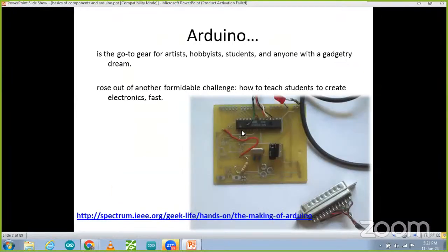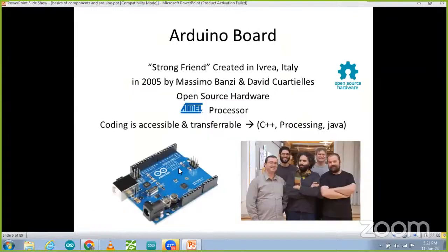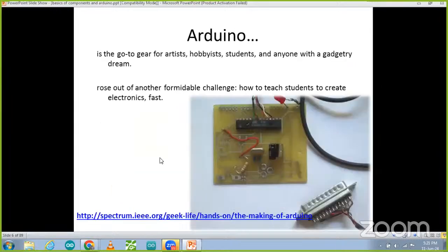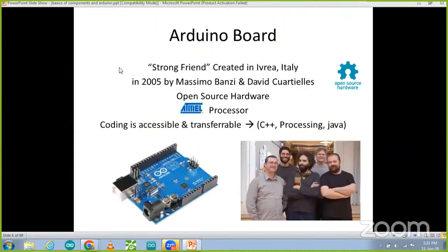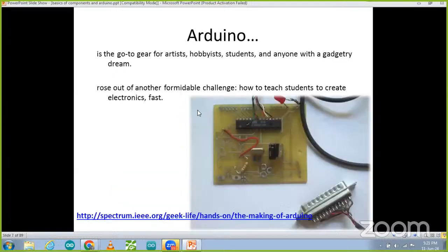So this one is Arduino. The beauty of this Arduino board is that you can make your own customized board also. Customized means you do not need to use the complete board when making your project. You can use this small board directly, and mount this IC on it. This is the Arduino IC. You can program this IC using the Arduino board, then remove it and deploy it in your project directly, so that you can save project cost.